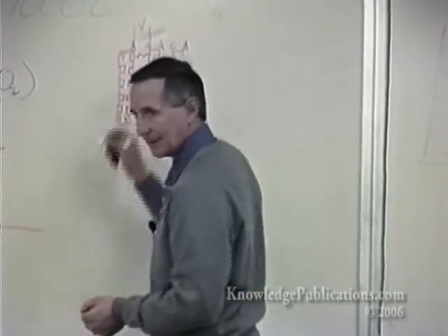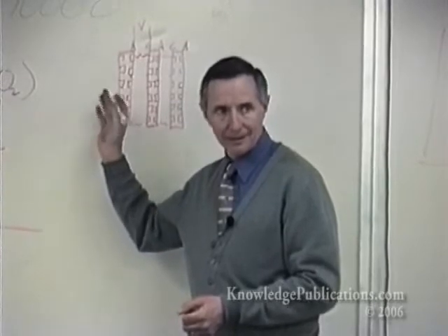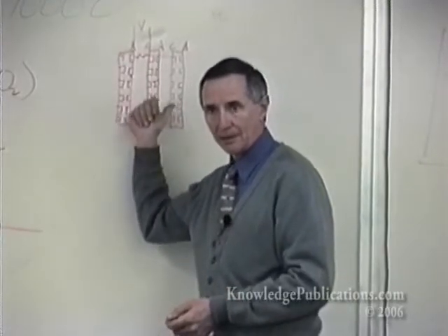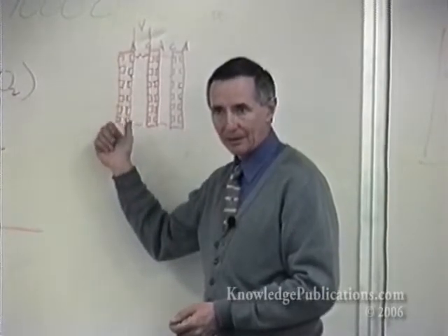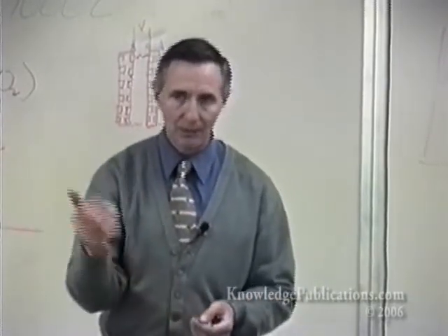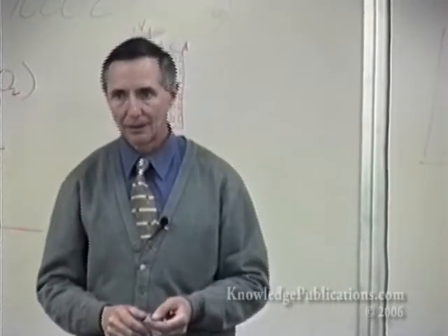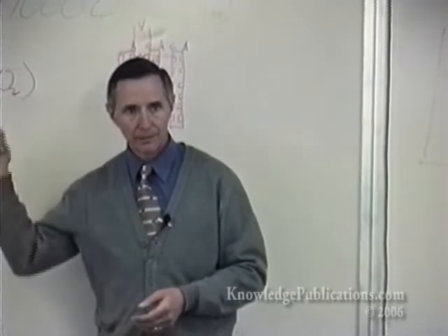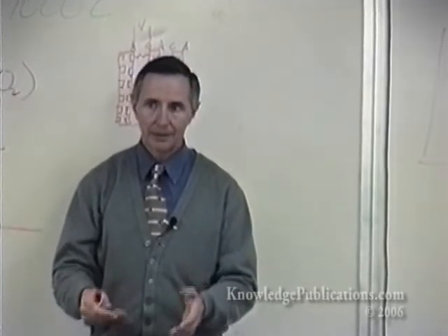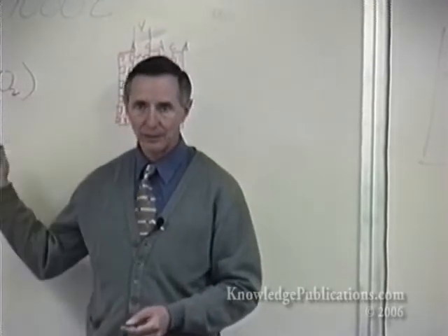So finally you get to this point, and you've done all those things, and still it isn't satisfactory in the voltage. And you start looking with a microscope at the problem, and you find that you're overloading the catalysts. The catalyst that is doing the job is heating, so to speak, because it has too many electrons going out of it towards the external circuit, too many ions going out of it to the internal circuit, and it's the bottleneck. And that's usually, in round numbers, where we put our money. We put more money in more catalyst. And that's true on the phosphoric acid as well. If you're not satisfied with the voltage you're getting at the current you're needing, add more catalyst. Or put the catalyst at a smarter place.